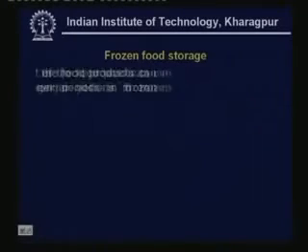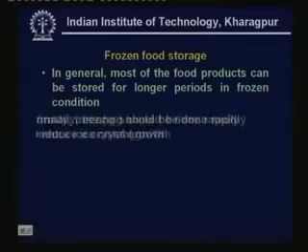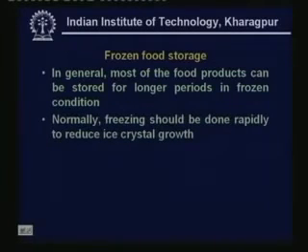Let's look at frozen food storage. As I mentioned earlier, frozen foods can be stored for a longer time compared to fresh foods. This is because of the reduced bacterial activity. And normally freezing should be done rapidly to reduce the ice crystal growth. This is very, very important. That means not only the final temperature is important, but also the rate at which the food products are frozen. You have to rapidly freeze the food products so that the ice crystal growth can be minimized.